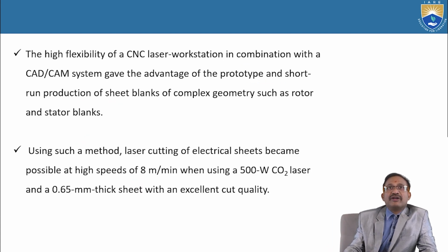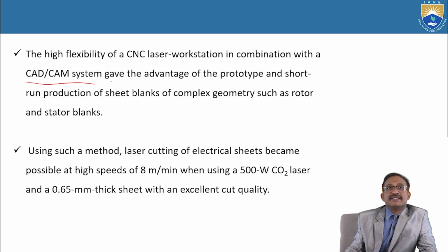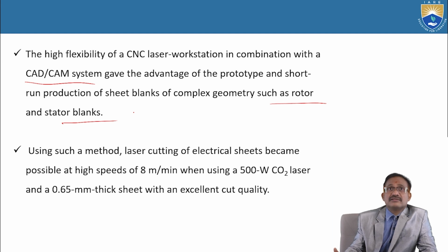The high flexibility of a computer numerical control laser workstation in combination with a CAD CAM system, computer aided design and computer aided manufacturing system, gave the advantage of prototype and short run production of sheet blanks of complex geometry such as rotor and stator blanks. So these profiles are very complex. We can cut them by using these laser workstations only. They cannot be machined with conventional machining processes.